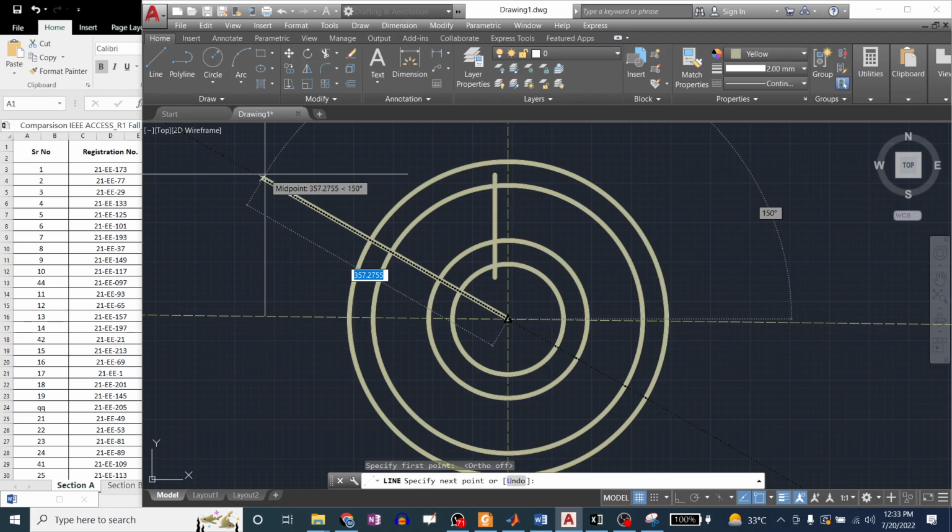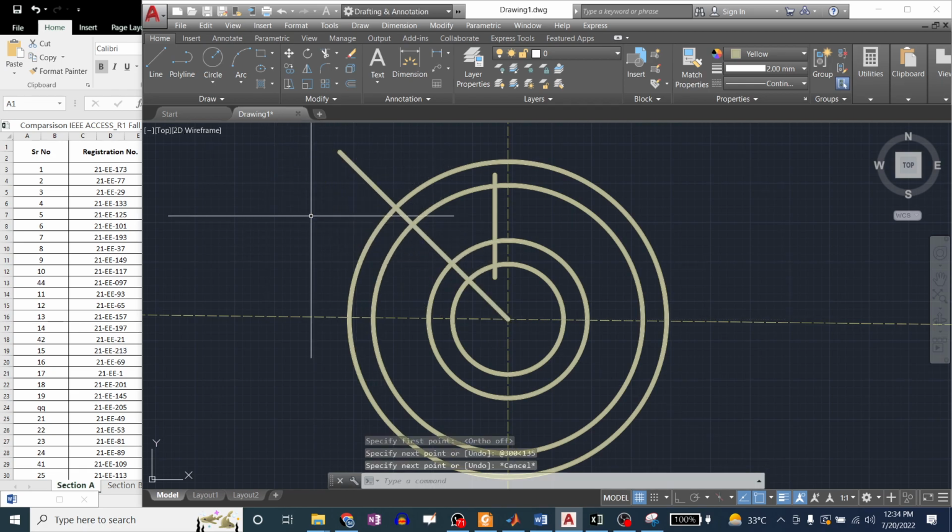So F12, you can press F12 if you want to write in coordinates, for example with angle. Then for example length is 300, less than sign, and 40, this angle is 45, but in this second quadrant, mean 90 plus 45, mean 135. So angle is 135 degrees. Press enter. Okay, so this is done.